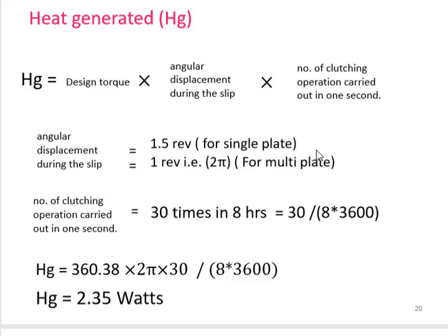We know when the discs are operated, there can be a slip that can take place between the friction plate and the clutch plates, and when the slip happens there is heat that is generated. Now if the heat developed is beyond the permissible limit, then wear and tear will take place, and hence to avoid that we have to see that the heat generated is within the limit.